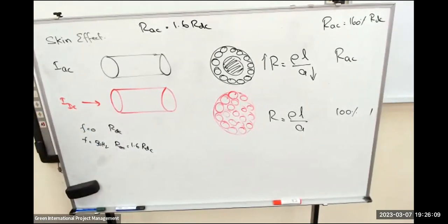As an electrical engineer, I am handling 50 Hz. For you electronics engineers, the same conductor carries communication signals, in the range of 10 kilohertz, 10 megahertz. So there also there is a significant gap. For electrical it is 1.6 times, especially at power frequency. If you go for communication signals, the resistance value increases even more.